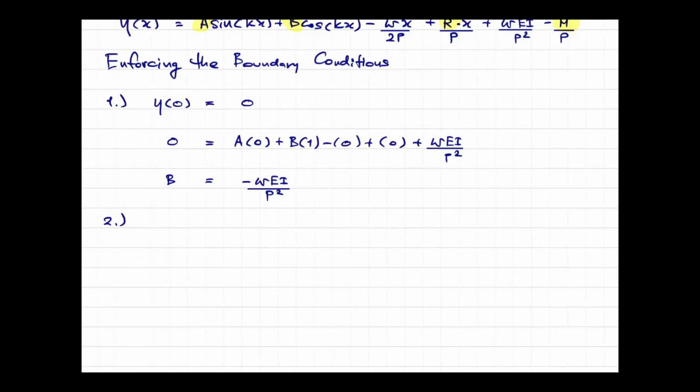Second condition. Over here we see that this beam is fixed, so you cannot use the force boundary condition, right? You have only the displacement boundary conditions. And the second thing to use is the slope. So dy dx equals minus what?